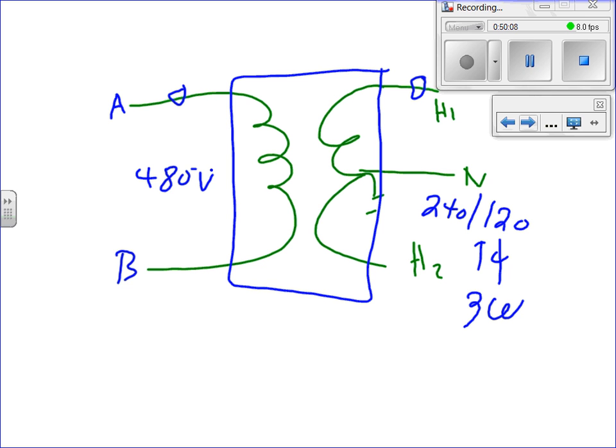But you would never do that. If you have a three-phase service coming to your building, you run with three-phase everything. It would be less than intelligent to put a single-phase panel when you have a three-phase system. Always run three-phase everything. But if this is your transformer and the voltage is 480, it could be 480. If your voltage is, say, 208, it could be 208 volt.